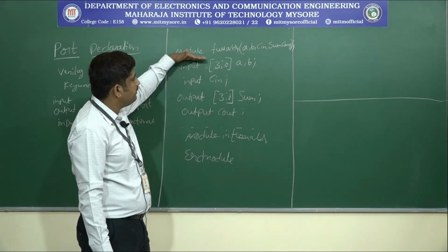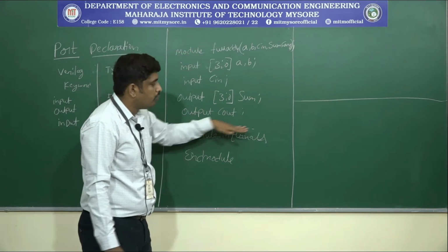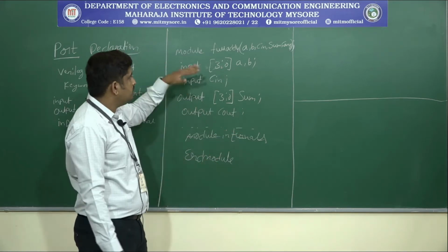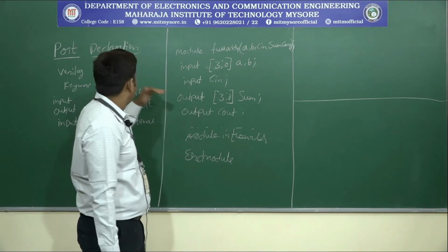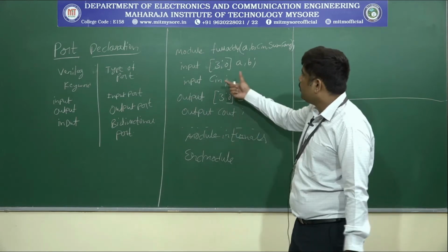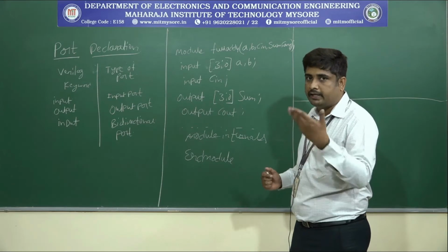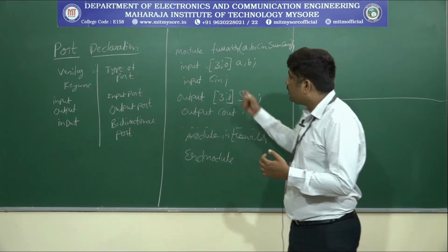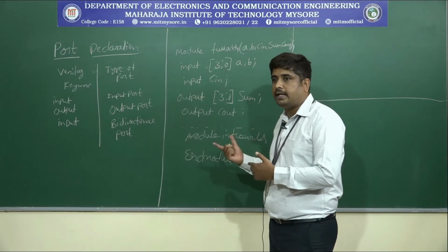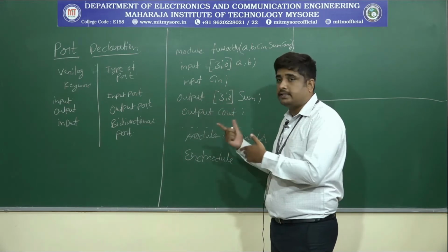Then after this, this is the ending of the port declaration. After this you have to mention the logic, that is nothing but the module internals. Next you have to write end module. This is the example for a 4-bit full adder, that is port declaration. Here input ports as well as output ports. Usually we access nets or wires, okay, but output should act as a register. Why should output act as a register? Let us take one more example, then you can easily understand.